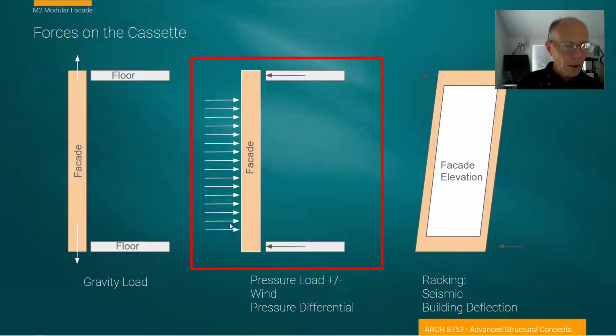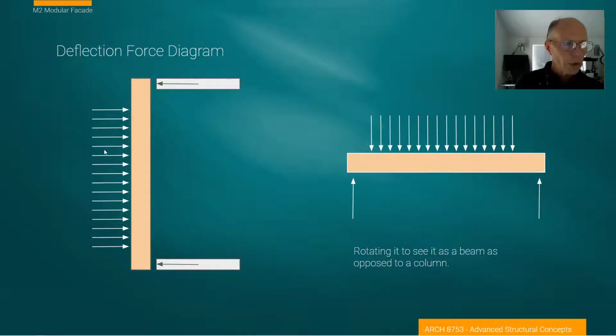We'll get an idea of how we would calculate that applied to our facade. And then we think about how those wind loads are supported back to structure. So we can look at our assembly as a free body diagram, a simply supported beam, with the two supports being the floors, and the uniformly distributed load being a constant uniform wind pressure along the surface of it.